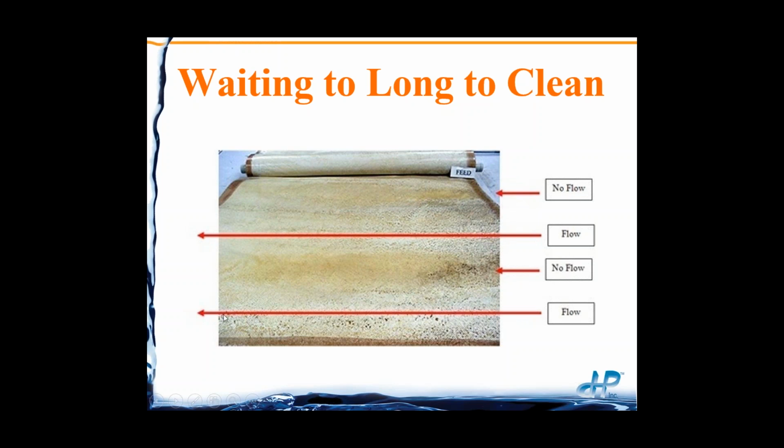So because of that, this is going to make our cleaning very, very difficult, especially if you're just using a standard cleaning procedure that says something like mix up your chemicals, get the temperature right, get everything dissolved, then circulate for an hour, soak for an hour, circulate for an hour, rinse, and you're done. Well, that might work if you clean at an early stage.